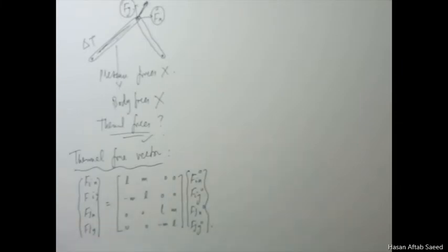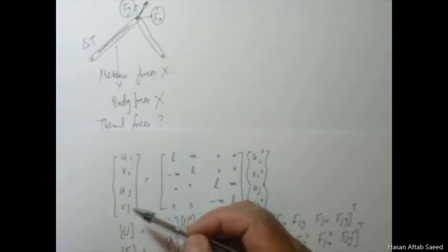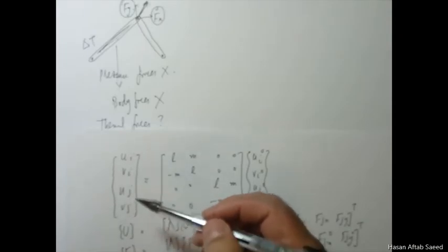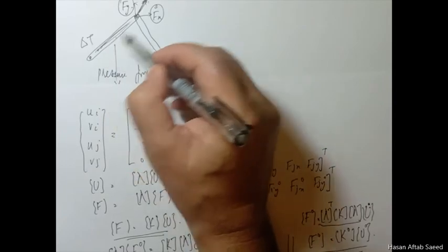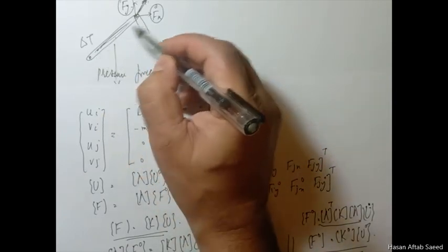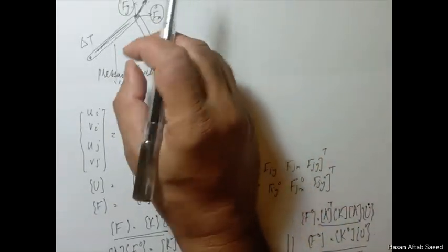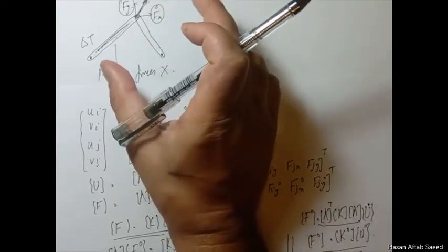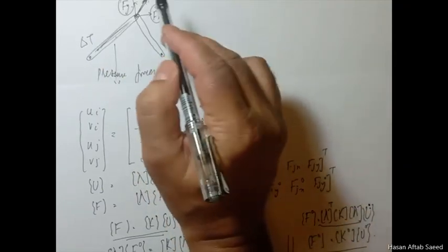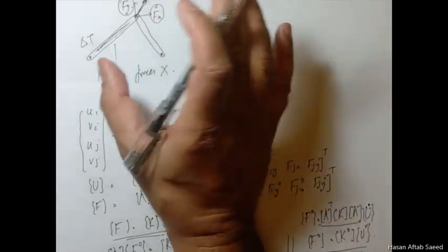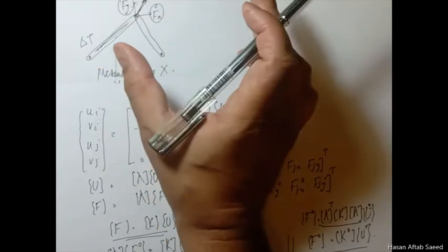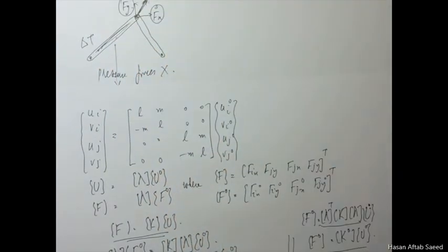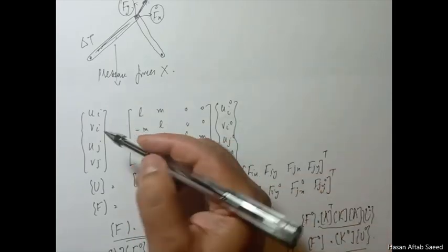Now, in a similar way like we did last time, we had said that these Vi and Vj are not relevant for us, because in the local coordinate system any element only extends or contracts in its original coordinate system. There's no perpendicular extension or anything like that. If there's a motion, then that is just a rigid body motion, just a change of angle. It has nothing to do with stresses or strain. Similar is the case with the forces.